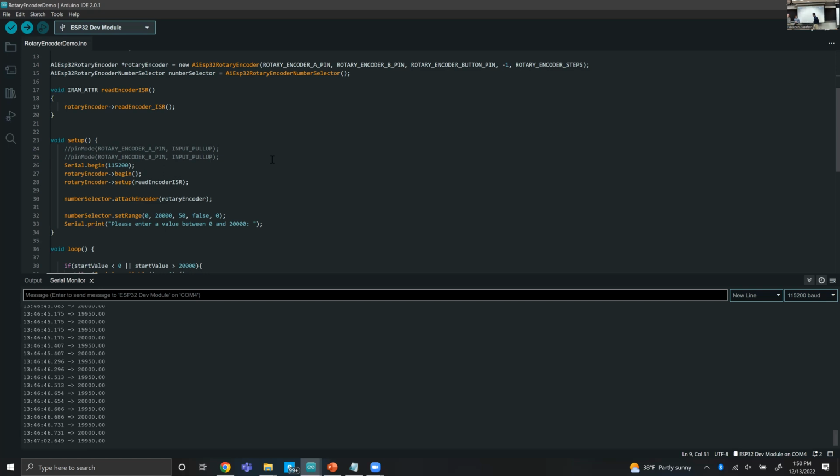The second thing, let's say you say, okay, I want to go to 2,500 RPM, which correlates. So what I see here should be RPM on the screen, doesn't matter how it rotates. And I see 2,500. In your control loop, there's no sensor checking if the motor is actually rotating at 2,500. It's a one-way, it's an open loop. So if the motors they choose have encoders, you're going to read that number back to make sure it is 2,500. If not, it has to keep feeding. This won't change, but your PWM has to change until the motor encoder says it is 2,500.